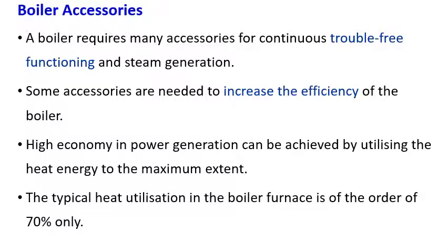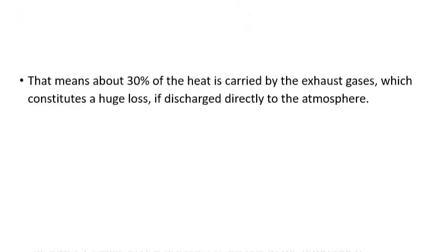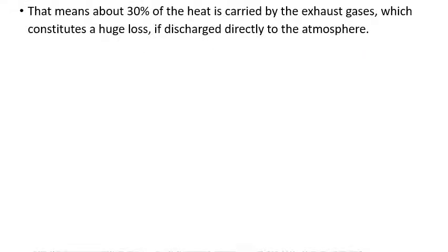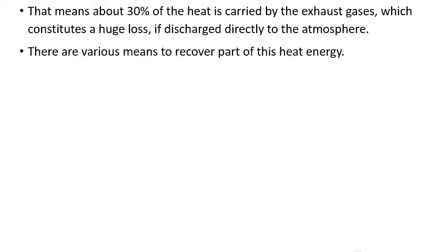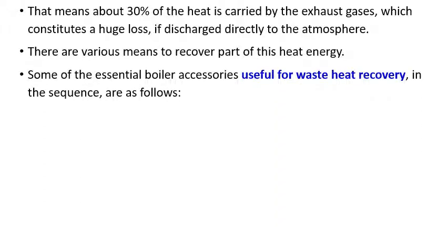Generally, the typical heat utilization of the boiler furnace is of the order of 70% only. That means the rest, 30%, will be left to the atmosphere or sink so that it cannot be recovered. This means that 30% of the heat is carried by the exhaust gas, which is a huge loss if discharged directly to the atmosphere. The various means to recover part of the heat energy are: